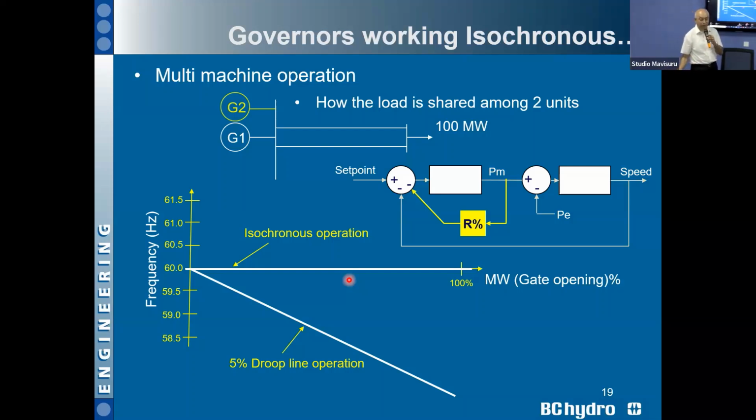Whenever the load is 0, you have an operating point like that, because your power is 0, your mechanical power is 0, so therefore the output coming over here is 0. That means it's working as a normal governor. So it has a set point of, in your case, 50 hertz. In our case, it's 60 hertz.